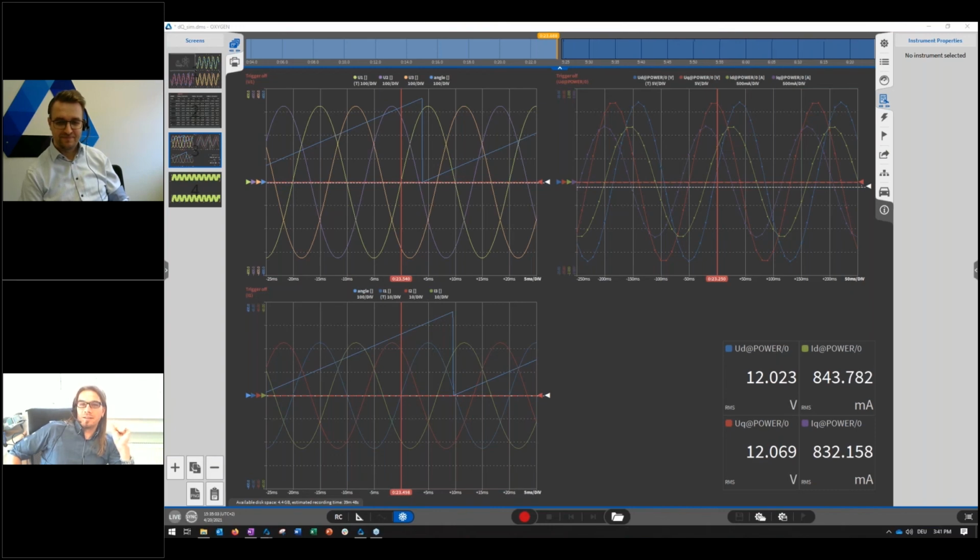And last but not least, Ivica, I think that was also a feature you requested, very powerful, which is the support of loading and decoding CAN signals with ARXML files and not only DBC files anymore. Yes, very important for automotive customers and partners who are getting more and more ARXML files to decode CAN messages.